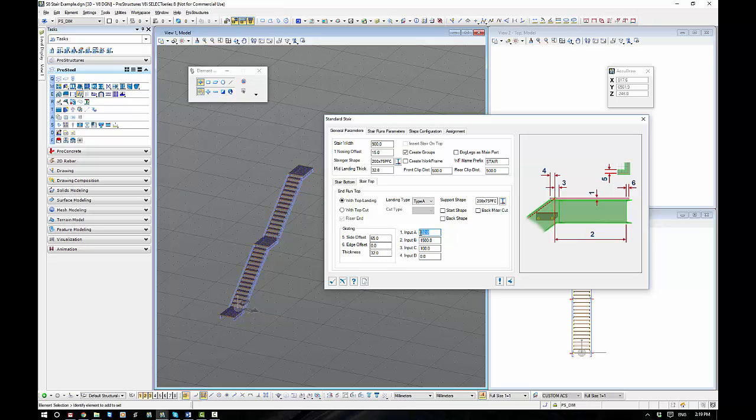Input 1, now this is pretty important. The top of the, this is referring to where does the steel work start. So it's the grating thickness down. Okay. The other key important point is the IP of the stairs. Okay, so I want a landing of 1500. I would like my support shape, if I have one, to be 100 back, and the grating there is 32, of course.